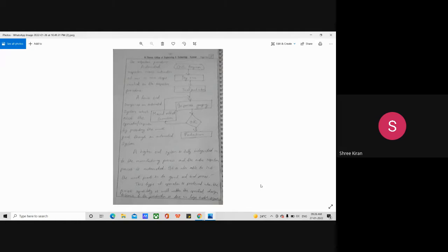So automatically the production rate will be high, and the possibility of getting errors is also always high. It might be a defect of the angle, a defect of programming, a defect from the wear and tear of the cutting tool, or a defect of the cutting angle. So many factors have to be considered and have to come in the inline process in order to achieve a good product.